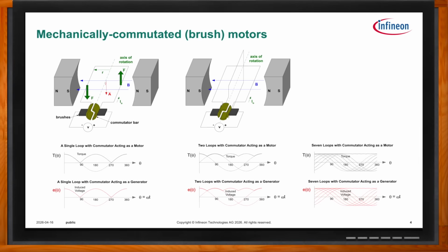the same structure, but now you have a two-pole motor with two loops of wire. And now you can also see in the torque curve that I have a much smoother total torque from these two wires. So for a shorter period, instead of going 180 degrees, now we only go 90 degrees per wire. And so it's going from its kind of sweet spot of minus 45 to plus 45 degrees. Then it commutates to the next wire and so on.